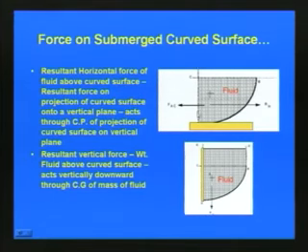In this case, this is the vertical plane where we are projecting this curved surface, and that will be the resultant horizontal force, and then it will be acting through the center of pressure of the projection of the curved surface on the vertical plane. So, this will be the center of pressure where it will be acting. The resultant horizontal force is acting in this direction, and with respect to the vertical projection, here it will be the center of pressure.